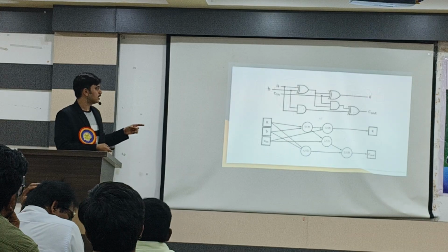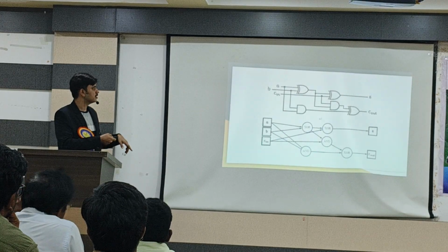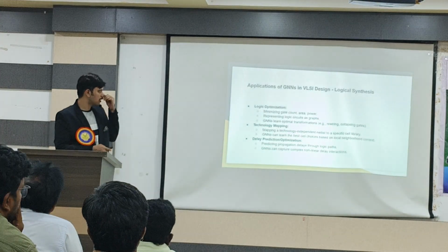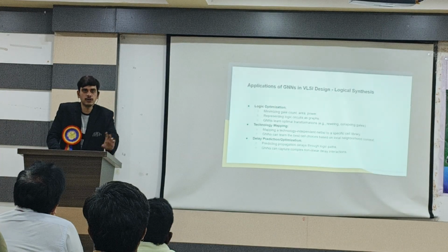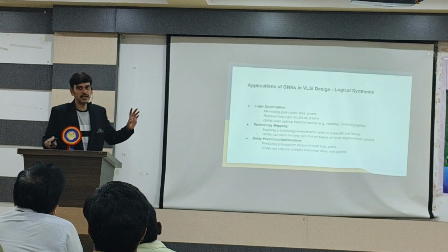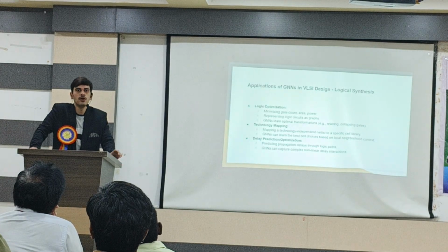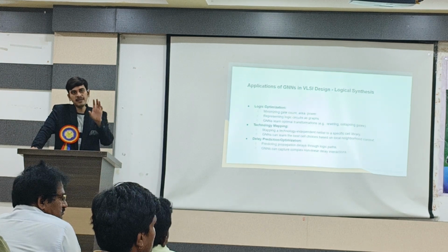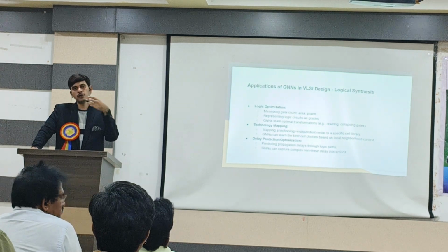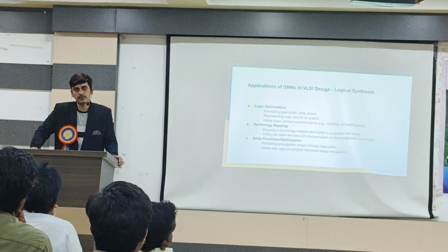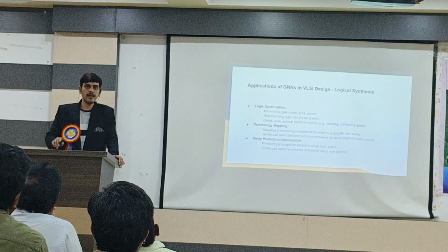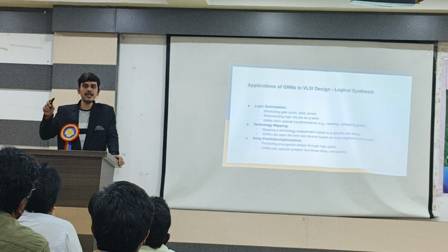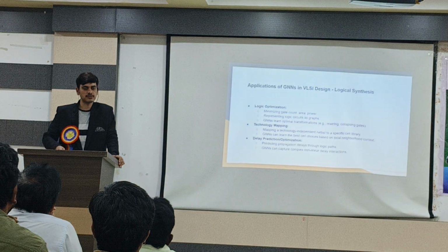Here, logical synthesis. So what do I do in logical optimization? From here onwards, we use the RTL language, right? So we do the synthesis, physical aware and non-physical aware. Placement aware, these things go up to 3 or 4 months actually. The hardest part is the floor plan, because the PNR always tries to change.